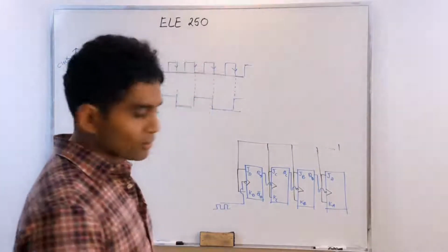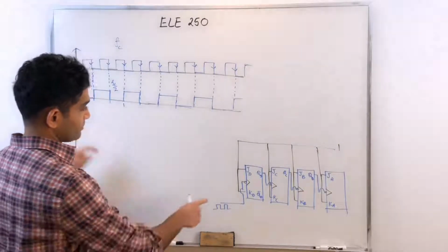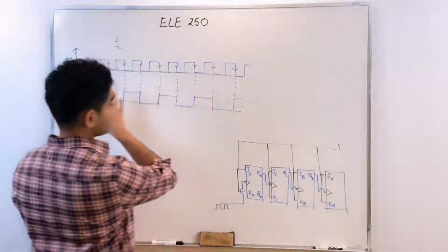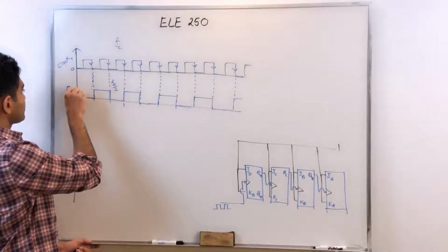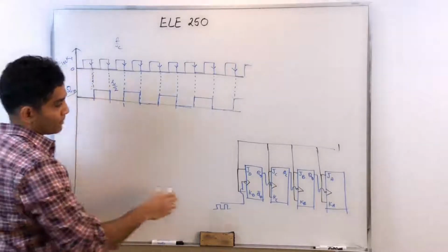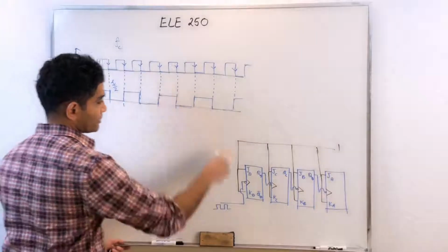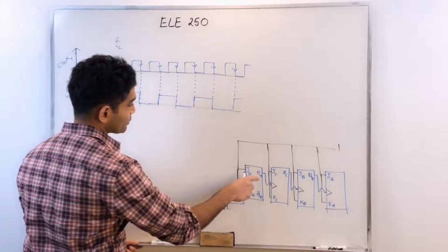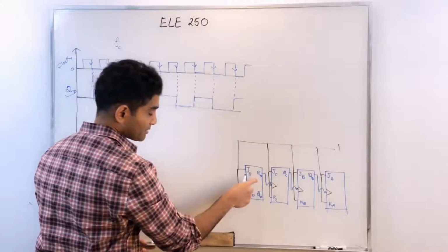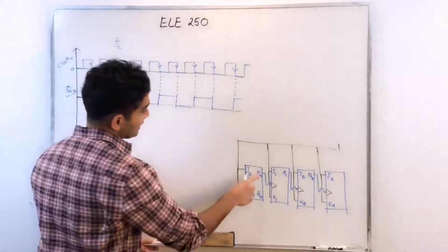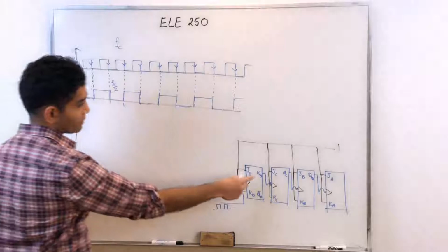I would like to see what kind of a function it does. Okay. So this is what I have. Again, what I have analyzed here is QD, right? I can basically call this QD, because I'm applying a clock directly to this flip-flop, and I'm trying to monitor QD, and of course my J and K are both tied to 1. That means I'm configuring this flip-flop in the toggle state, and I'm monitoring QD as a function of clock. And this is exactly what I would get for this particular flip-flop.